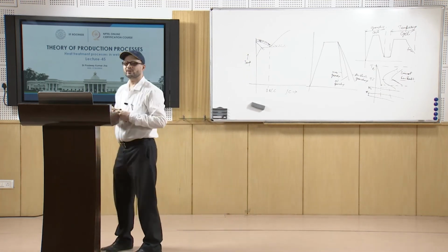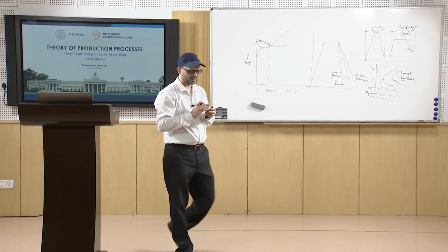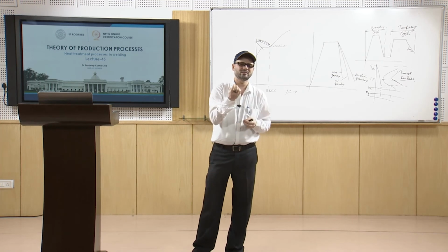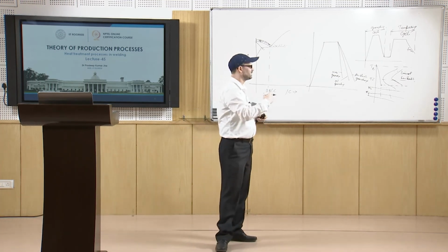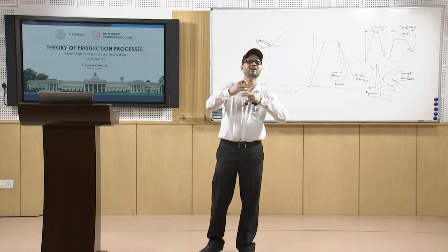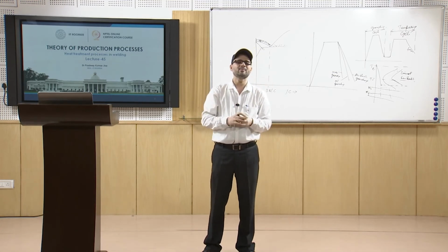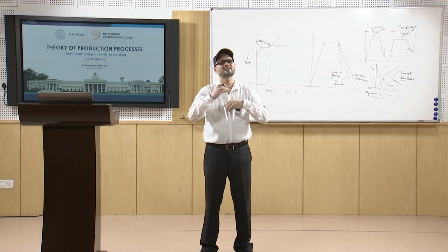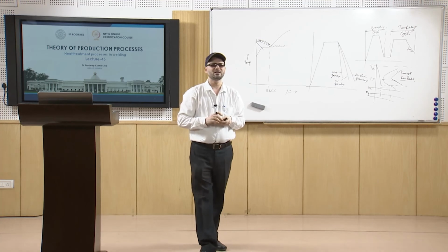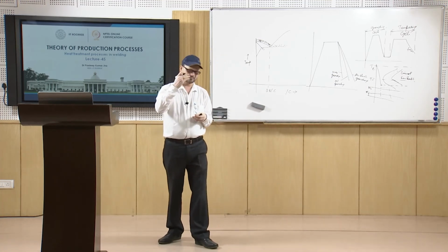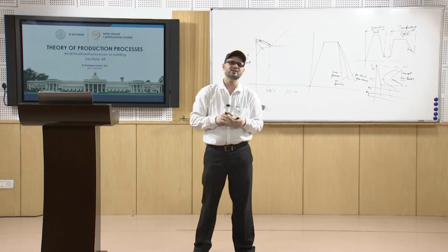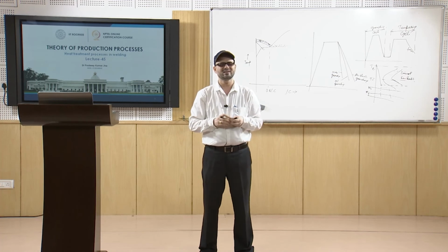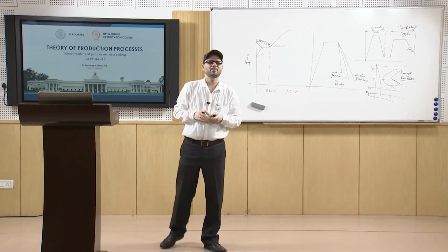Basically, the solubility now is less. So once we further heat it to some temperature, the phase whose solubility is less tries to come out as precipitate, and that improves the strength. That is known as the precipitation hardening mechanism. This process of increasing the temperature, retaining for some time and then cooling is known as aging treatment, and aging treatment is of different types.